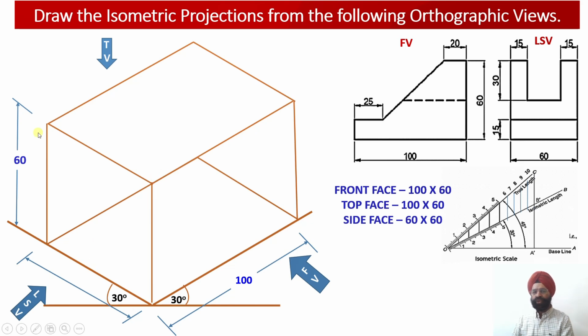And you can see, because it is a square prism that we have drawn, we have got the overlapping of this edge, that is the top edge over here, the outermost one, and this edge of the base over there. So this becomes a perfect square. Only then will these two edges overlap with each other. And then from this corner, we have to draw the vertical edge corresponding to the back face of this particular solid. So this is the front face, and this one is the back face of the solid. Again, this edge height will be 60 millimeter, and it will be parallel to the y-axis.